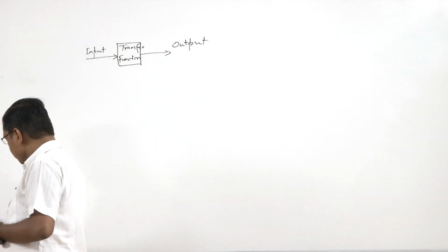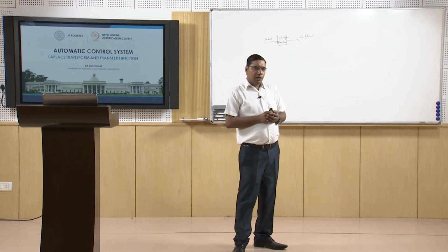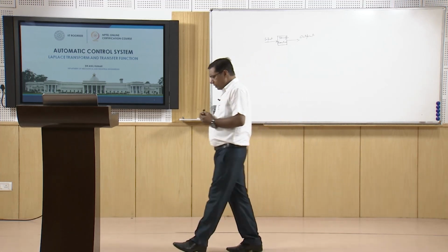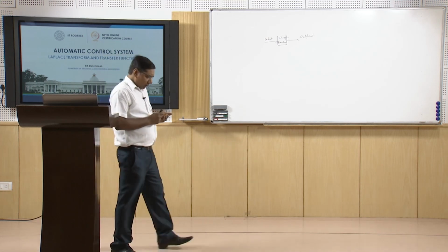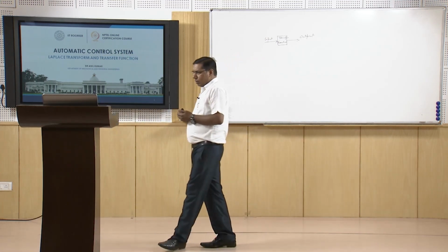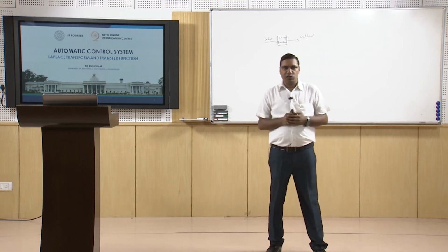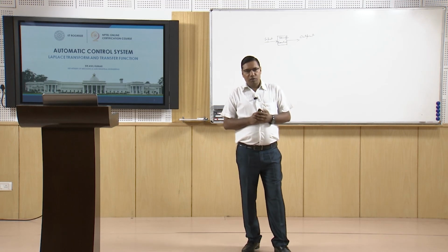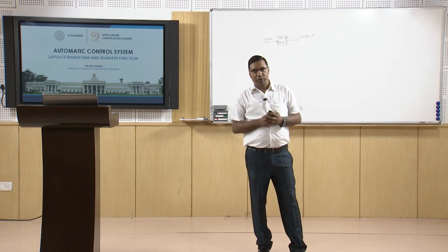So to find the transfer function we need to use the Laplace transform, because Laplace transform is a technique that can be used to convert the differential equations or integral differential equations in time domain to algebraic equations in complex frequency domain. So when we have to solve a differential equation, we can take the Laplace transform. We can shift our time domain to S domain. S is the complex frequency domain, and then we can come back by taking inverse Laplace from S domain to time domain, and we get the solution of that differential equation.